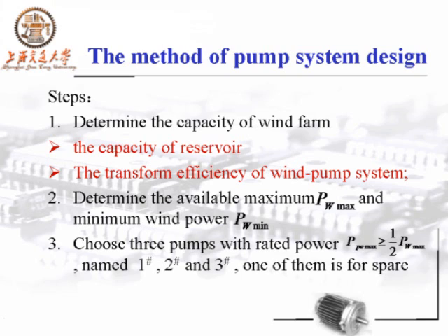Then choose two pumps, with the third one as spare. So two pumps with rated power at half of the maximum power.